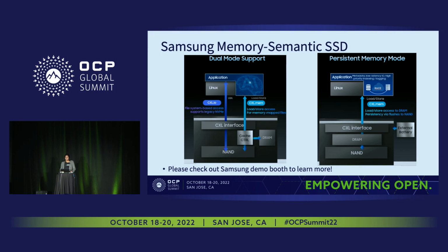So the next up is the Memory-Semantic SSD, right? People talk about TCO and how do you enable so much memory, the DRAM is not scaling as much as the requirements are, and how do you go beyond that? What today's TCO conscious memory expansion is doing is expanding over NVMe SSD and paying a software overhead and an IO tax to access this more than required amount of memory using block access instead of the smaller granularity 64-byte, 128-byte memory accesses that's typically required by this system, right?